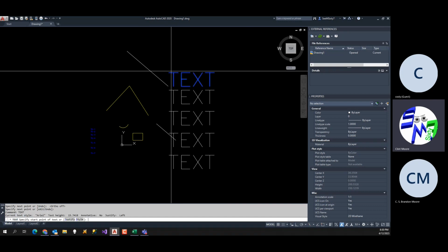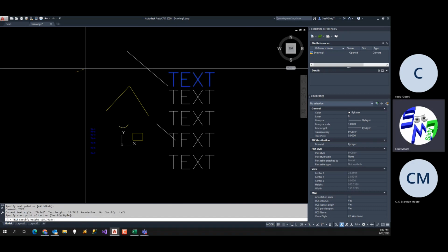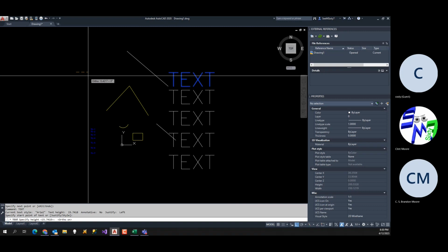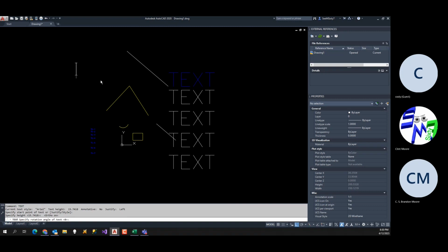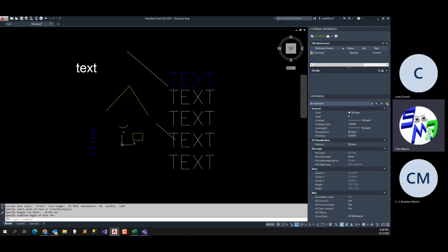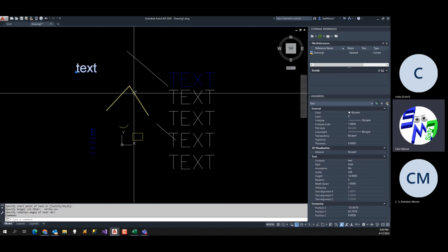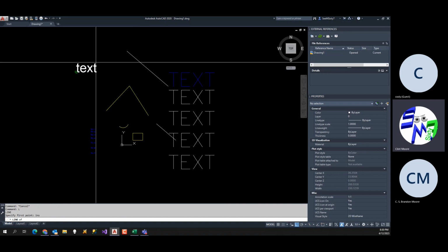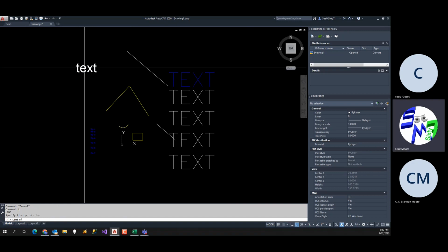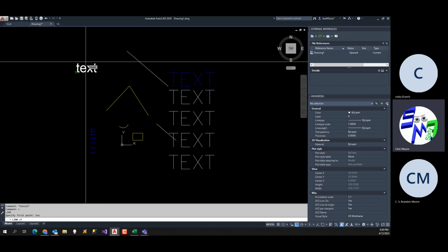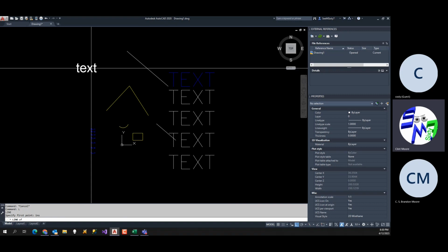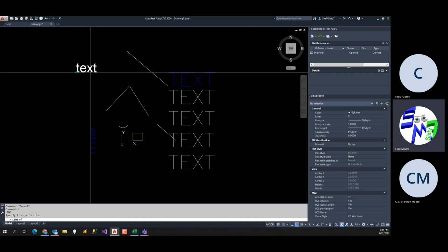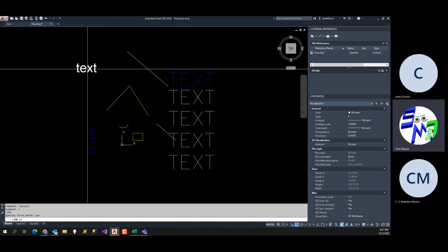Now I'm going to draw some text, and I'll place it here, and I'll make it big. And we'll call it text. Boom. Now this is my Arial font. Now watch when I try and do an insert from here. I have to see I'm actually over the text and it's not finding it. I have to go outside and hit the box that text would actually fit into before it actually finds it. So it's easy to get confused here because you're trying to find the insertion point and you can't find it. You get too close to the edge and it's pretty easy to find it. But if you try and pick anywhere inside, it doesn't work very well.